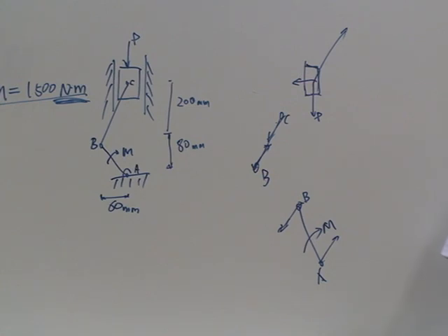We don't know, and we probably don't care. Because here again, we need to use moment analysis, correct? So we take the moment of this point A. We choose it as the point of analysis. Look at this number. There are only 2 moments inside this number with respect to point A. One is in this direction, the other moment is in the counterclockwise direction. So through this, we use sigma M equals 0.